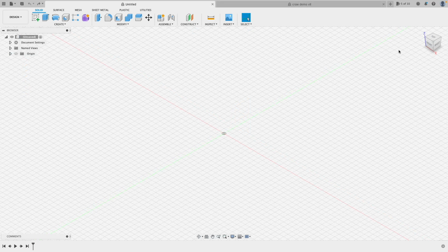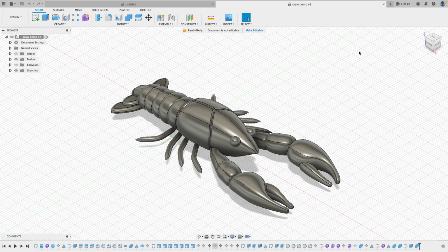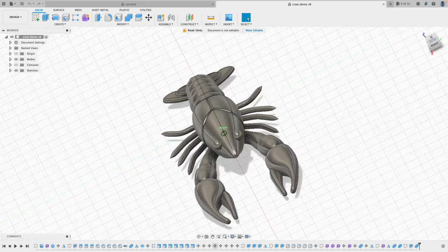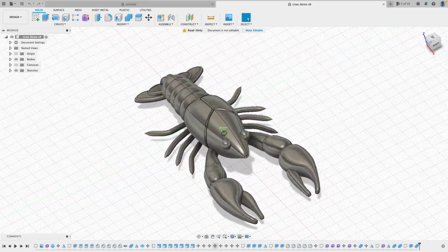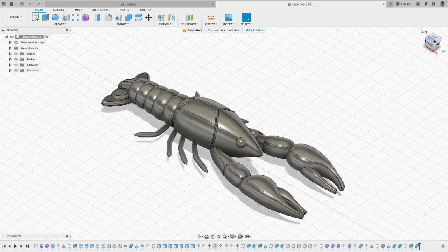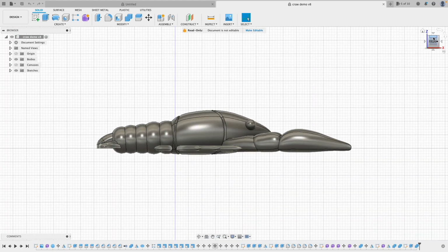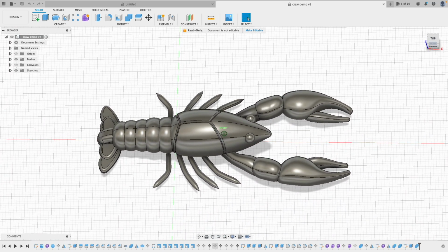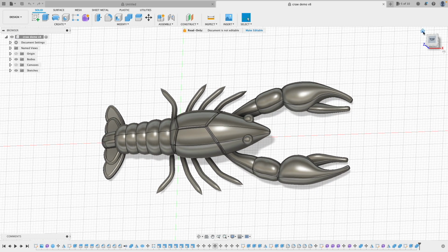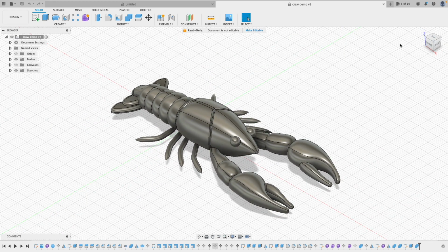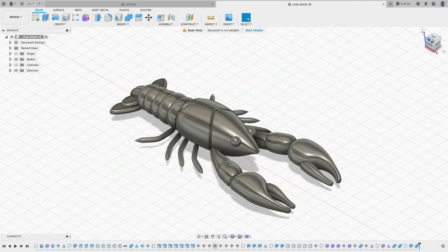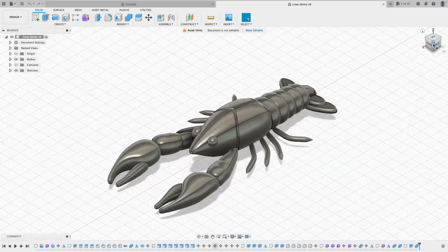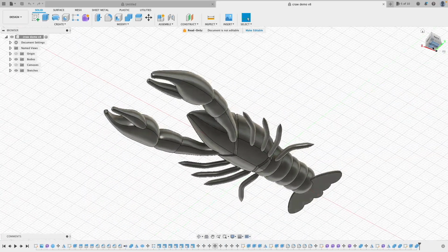On the right, there's a viewing cube. Let's load an object so it's easier to see how to manipulate it. So basically, you can drag the cube, and the object will rotate the way you drag the cube. And also you can click the predefined name on the cube, like front, and you can drag it, turn it, and also you can click the home and it will go back to the home viewing orientation. You can click the edge, the corner of the cube, look at from the bottom.